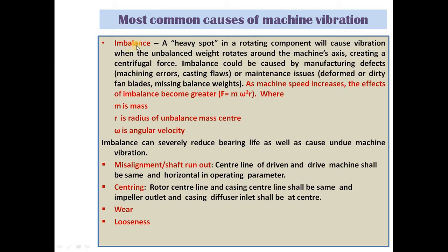What is imbalance? Imbalance is a heavy spot of a rotary component. It may come in the rotary equipment due to machining error, casting flaws, or maybe due to maintenance issues like deformed or dirty fan blades, missing balance weight, etc. And when